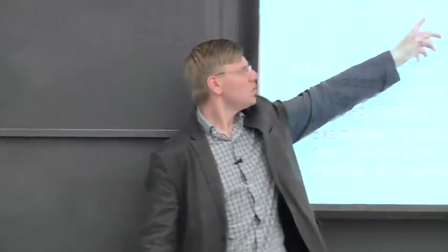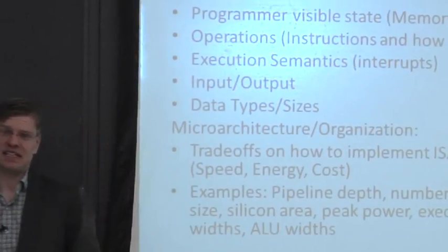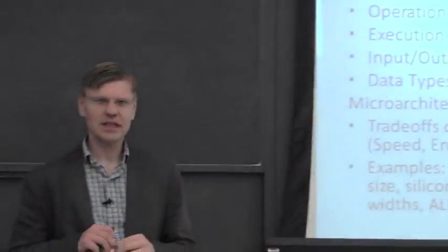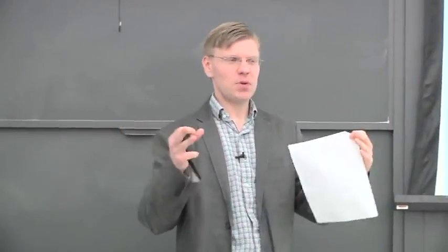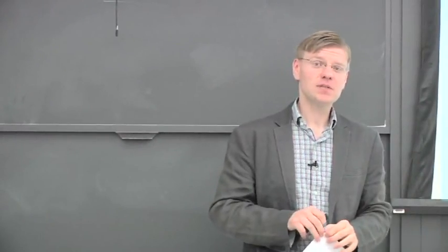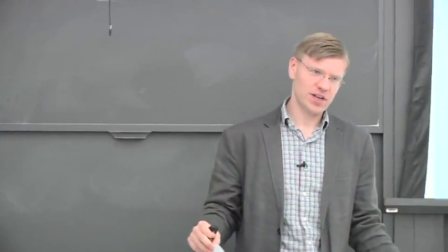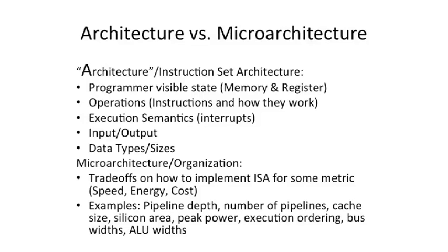Then there's more complicated execution semantics. What do I mean by execution semantics? Well, if you just say add takes two numbers, adds them together and puts them in another register, that many times does not encompass all of the instruction set architecture. You'll have other things going on, for instance I/O and interrupts, and you have to define in your instruction set architecture, or your big A computer architecture, what is the exact semantics of an interrupt or a piece of data coming in on an I/O? How does that interact with the rest of the processor? So many times the instruction execution semantics is only half of it, and what we have to worry about is the rest of the machine execution semantics.